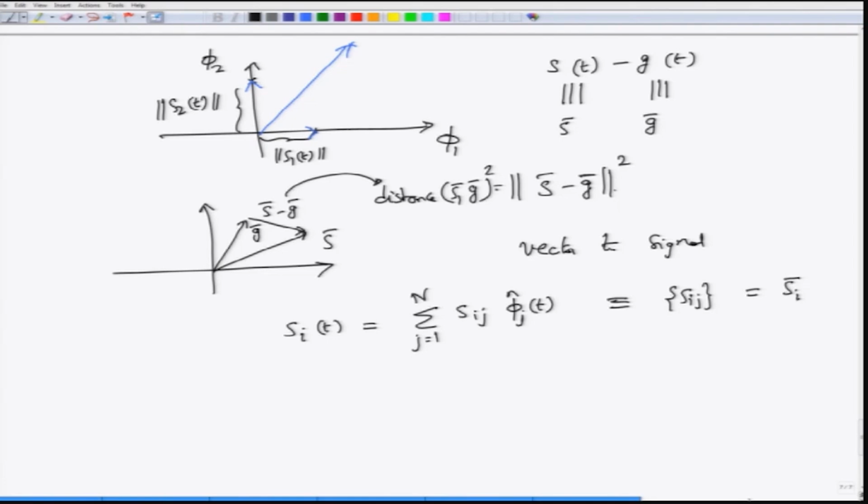These concepts of the distance between two vectors, and how to utilize signals as vectors, will be very important when we discuss digital modulation techniques, where we will see that ASK, BPSK, QPSK, QAM, all these waveforms can be thought of as vectors in a geometrical space. Even noise can be thought of as a vector in that space, and then we will be developing a lot of intuition about how to go about calculating the probability of error and all the other different metrics that are involved with this.